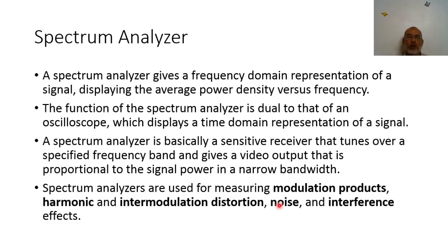For the case of an amplifier, for example, where we are interested in determining its dynamic range, we are going to change the input power and see the output power. We see when the output power is below the noise level, and when the power is slightly greater than the noise level. By measuring the output power as a function of the input power, we can see when the relation becomes nonlinear, or we can determine what is called the 1 dB compression, and so on. So effectively, any problem which can be described in the frequency domain can be measured by using a conventional spectrum analyzer.